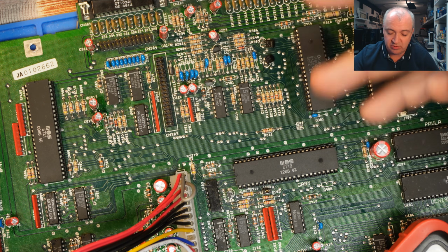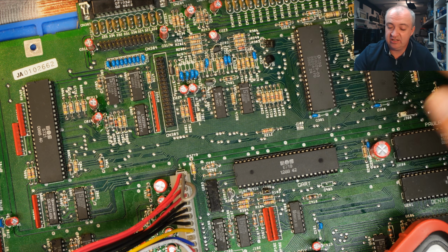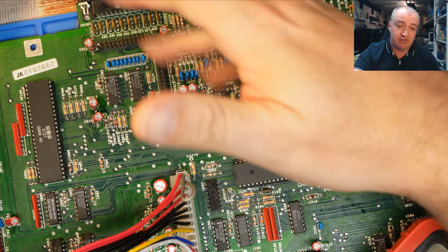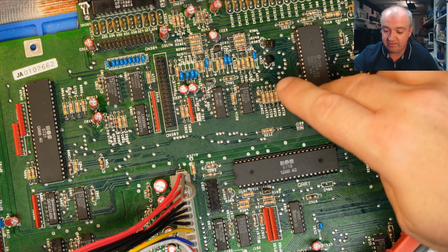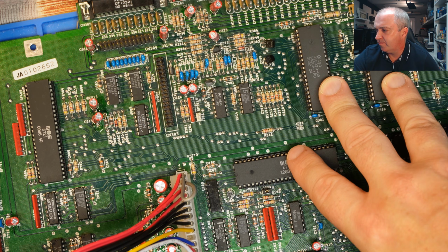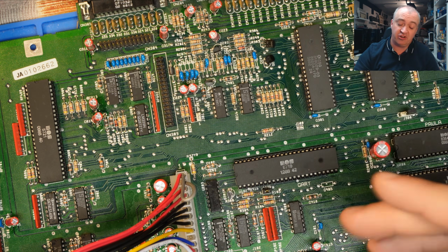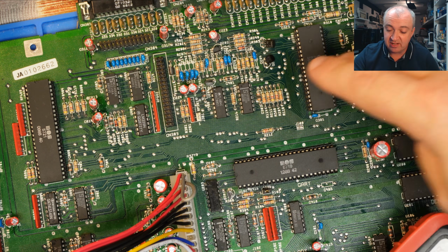That E clock runs at 1/10 of the CPU clock, and it is used by the 2 CIAs, the floppy port, and the serial and parallel ports and whatnot. Basically everything controlled by these 2 things. And presumably by adding the cap and the resistor to ground, we're just helping to stabilize that clock somehow.